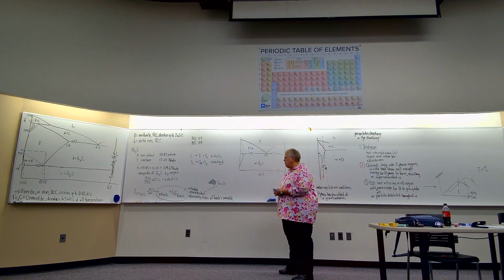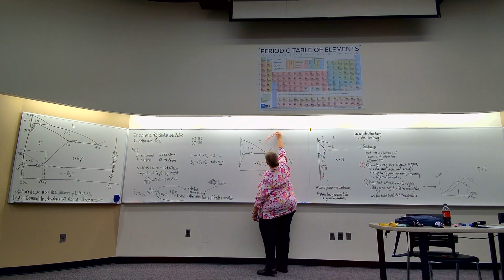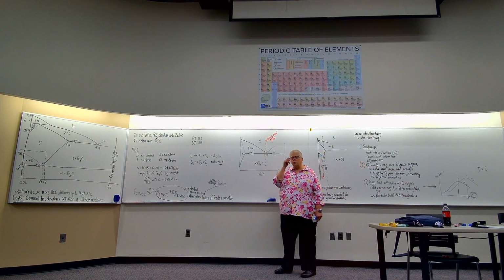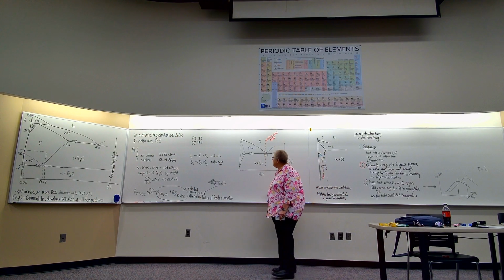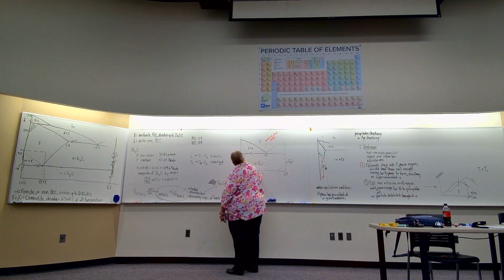So if we think about when we were talking about eutectic, we have a eutectoid composition, we have a eutectoid steel, 0.77 weight percent carbon. Typically, if you buy that steel, it's a 1080. We have off-eutectoid steels.